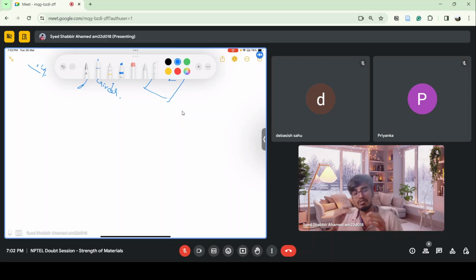So that also has to be as some design engineer has given, that this should be the strength of the concrete. So when you are manufacturing this concrete, that also should be maintained. Parallelly with the construction, you make these cubes and test them. If the cubes are satisfying those strength requirements, then you can say that this concrete which is used is safe for the design which was made.